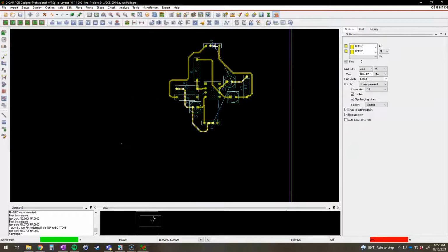And so this ground has to be connected to the same ground as there. Now, it also needs to be connected up here. So you see now I could connect it up into here. And what's nice is that by connecting it up into here, as I said, notice how these traces are kind of automatically spacing themselves for me. So I'll just go ahead and connect it right there. Now this is again where sometimes you have to think about, well, the line is the shortest distance, but that's not necessarily going to be the best way to go.